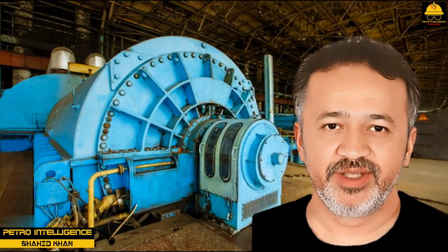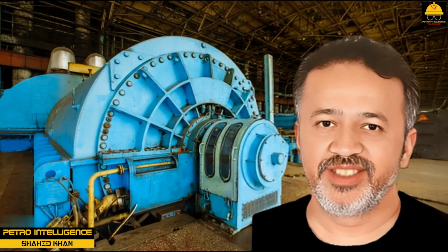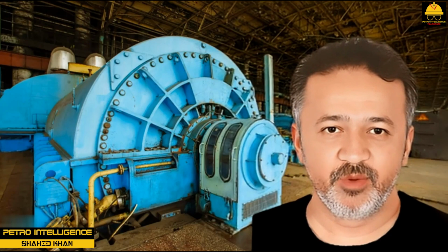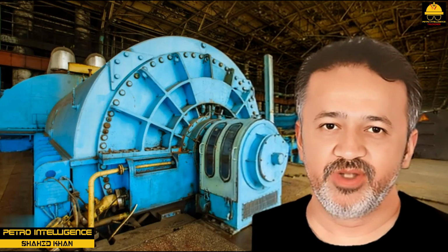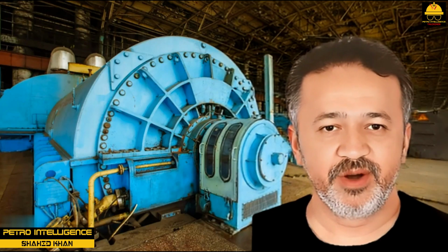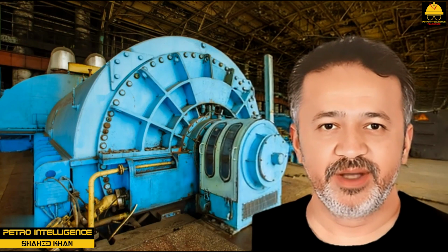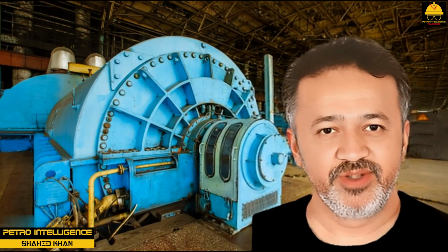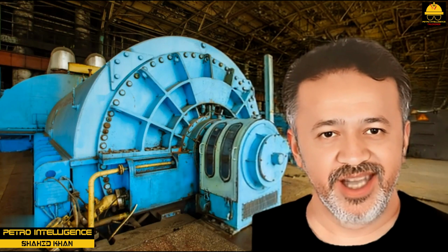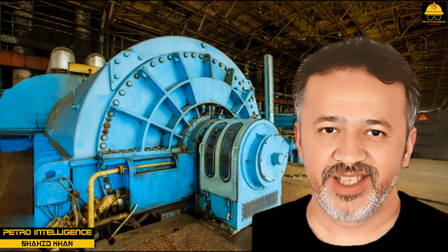Steam turbines typically are classified into the following categories: condensing, in which exhaust steam is condensed; non-condensing, in which exhaust steam is used in low-pressure steam applications; reaction, in which steam is discharged from a nozzle mounted on the rotor, and movement is a reactive response to the release of steam; impulse, in which steam acts upon the rotor to create movement; single stage; and multistage. Most plants use the impulse design.